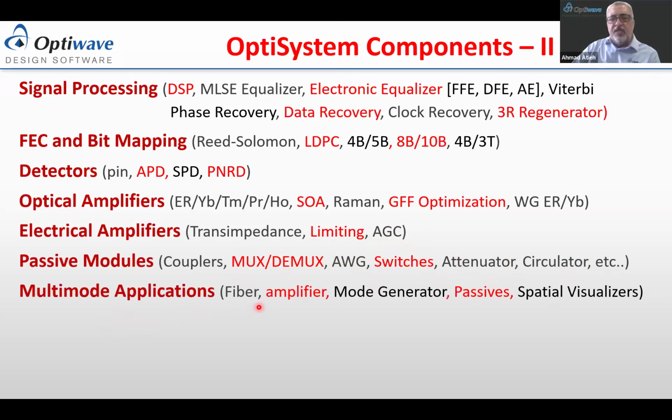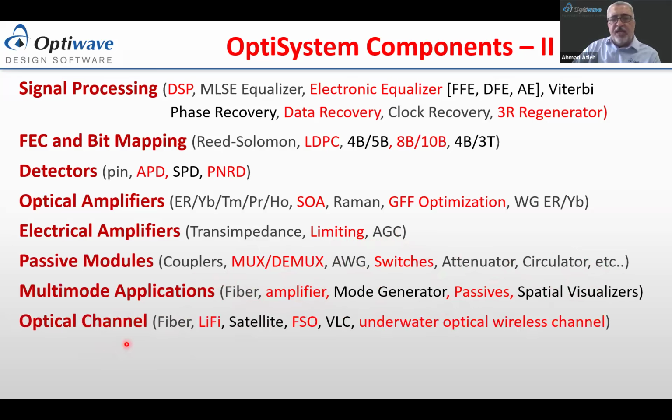Multi-mode applications, we support multi-mode fiber as well as multi-mode erbium amplifiers and multi-mode ytterbium amplifiers. There are mode generator components as well as spatial visualizers. Channels, we talked about fibers. There is a free space optic channel, which can be used for visible light communication or Li-Fi, satellite communication, as well as underwater wireless channel.